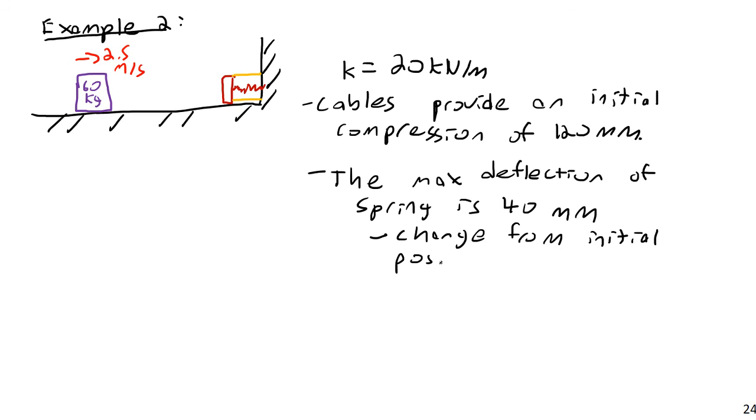So when I'm saying deflection in this case, I'm meaning the change from the initial position. Basically the spring is going to start out compressed 120 millimeters, and then it will compress an additional 40 millimeters after the package hits it.